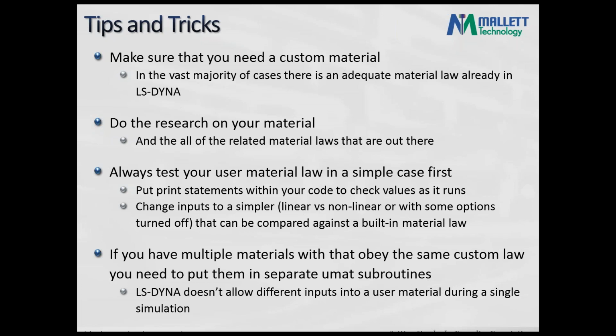And third, we do this all the time, and people who write code do this. You may want to test a very simple case first. You want to output all the steps along the way to make sure everything's going as you expect it to, and you want to test simpler cases when you can that can be compared directly against the LS-Dyna built-in materials, and make sure everything is running exactly as you intended to.